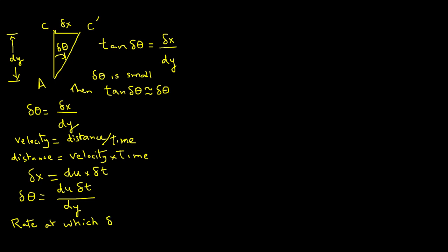So in the case of fluids, we must correlate our shearing stress with the shearing rate. So it is not only the force that is being applied, but we also have to consider the time. So the rate of shear, which is expressed as the Greek letter gamma with a dot on it, will equal the limit of delta theta over delta t.